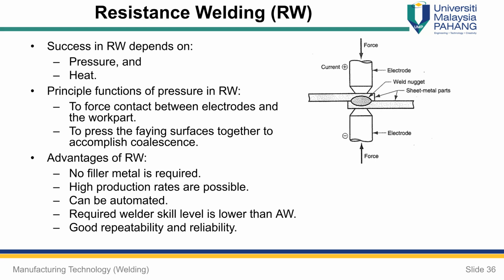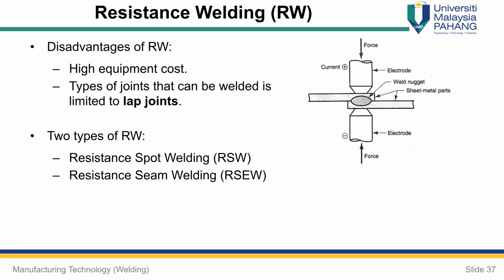Applications of PAW include automobile subassemblies, metal cabinets, door and window frames, and home appliances. PAW can weld any metal, even those difficult to weld like tungsten and bronze. PAW offers good arc stability, better penetration control, high travel speeds, and excellent weld quality. However, limitations include high equipment cost and a larger torch size that may restrict access in certain joints.